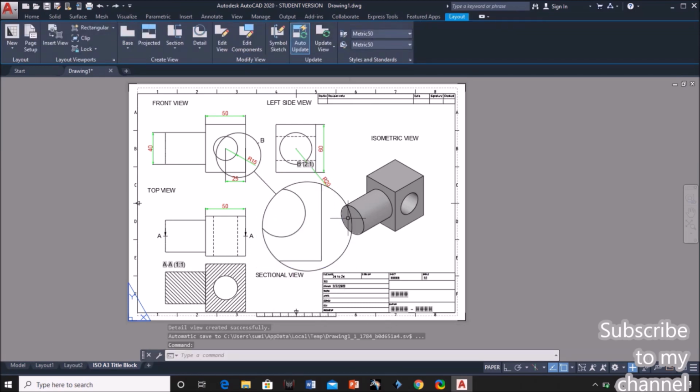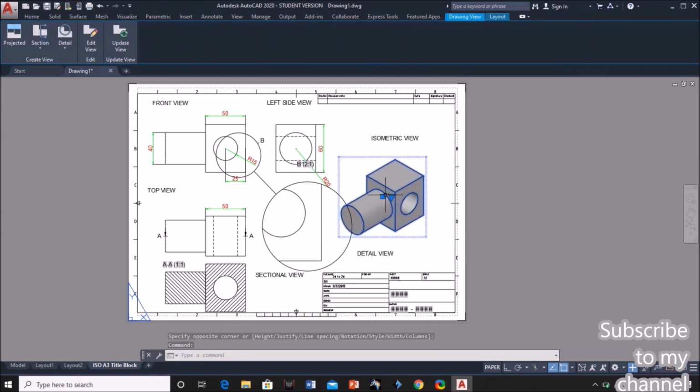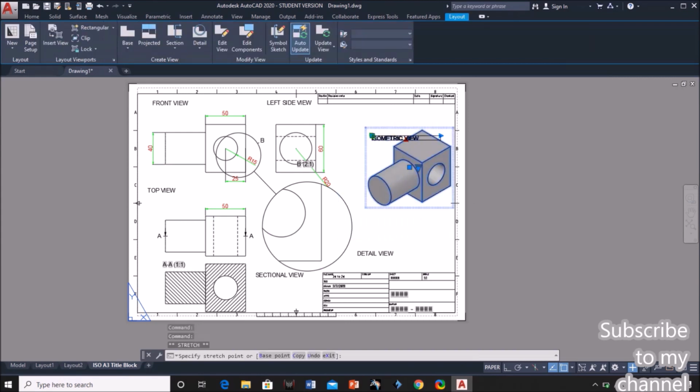So now I'm giving the name as detail view. Empty. Enter. Specify first corner, another corner, and specify the height 5. Enter. So this is about the detail view, and click on close. So this is about giving the text for these views.